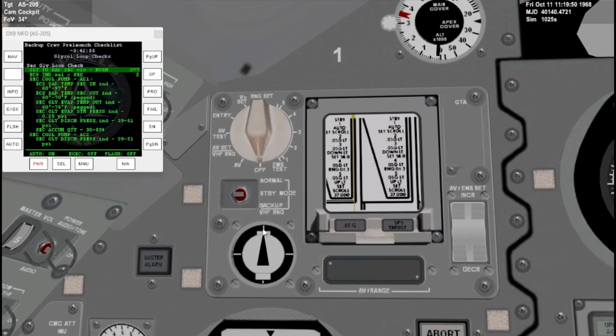lunar orbit to Earth. With that much delta V, we can skip out. In Earth orbit, it is not much of an issue, but you'll be very far away from your designated landing point. The horizontal indicators will stabilize the G-forces, but they will also cause the spacecraft to move right and move left. The down lift vector light will cause us to dig into the atmosphere steeper, incurring higher G loads.